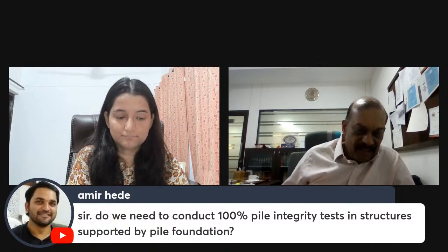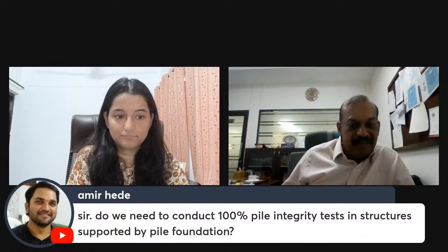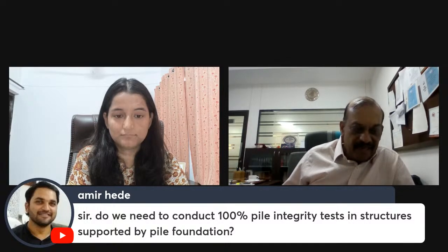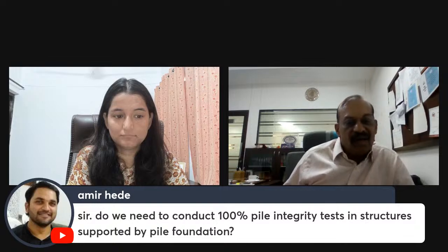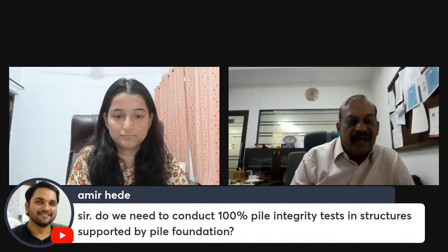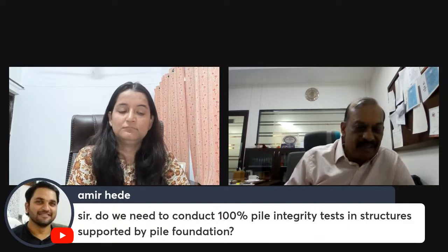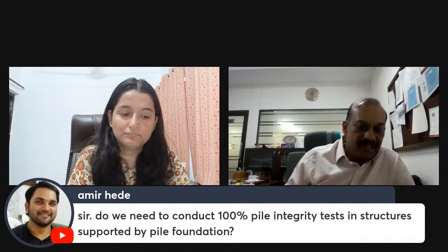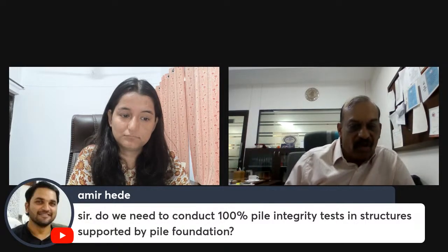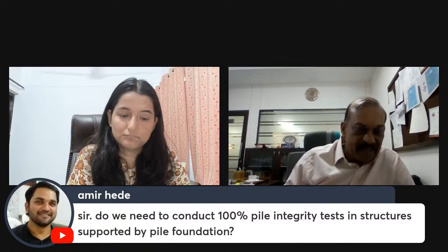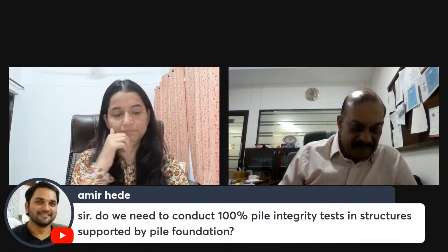But I would strongly recommend that you test 100% of the piles. Usually on a site you will find piles of different quality, so it is best to conduct the low strain pile integrity test on all the piles, because it's not a very expensive test.